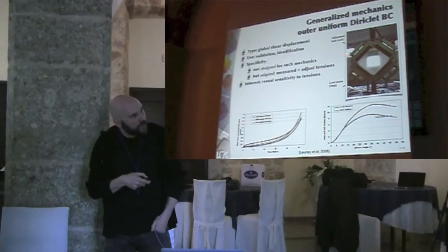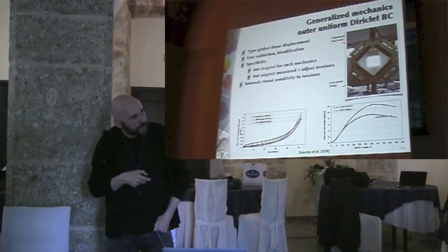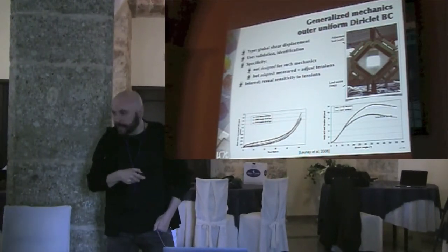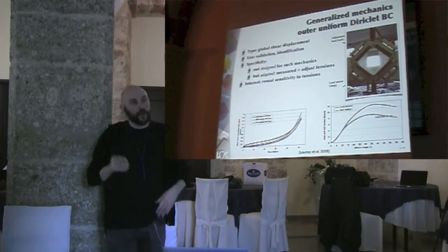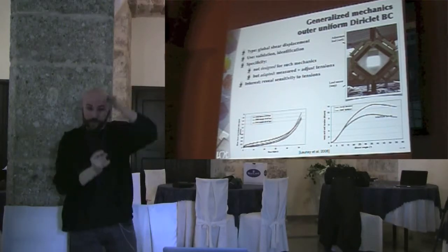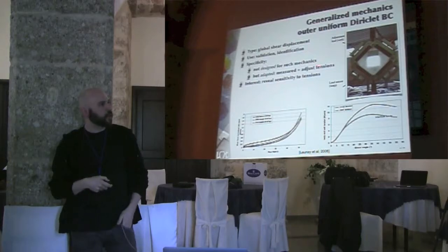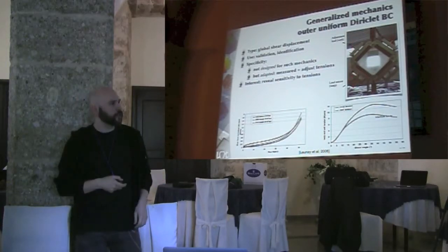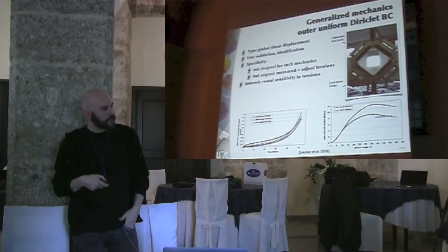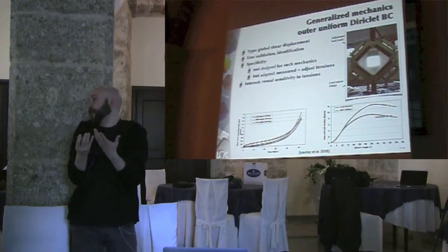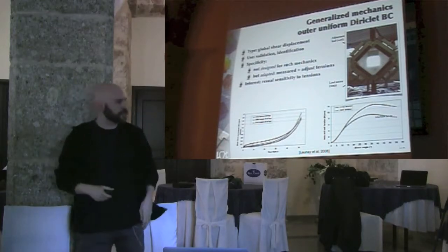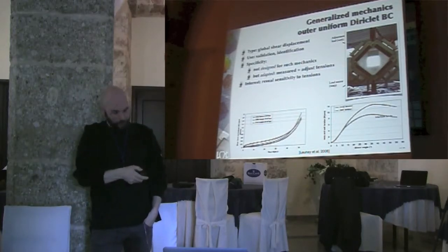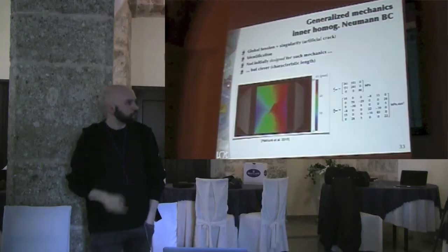Especially here, it's very clever because you have load cells that measure the biaxial tension, the initial one, and then the evolution of the biaxial tension during the shearing. And so you've also got an initial adjustment of the initial tension, and you can see that during the test, depending on the initial tension, the response changes. So this type of measurement is really interesting.